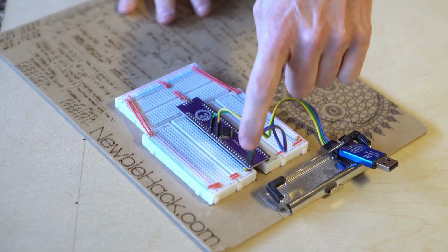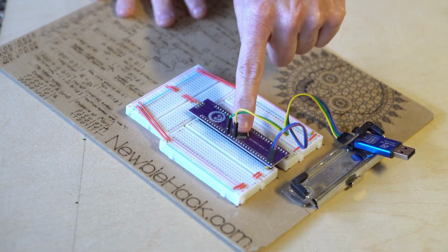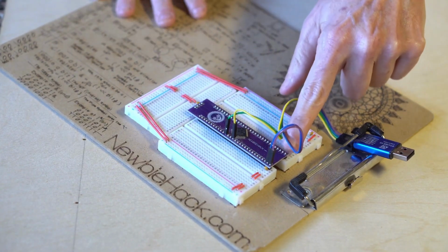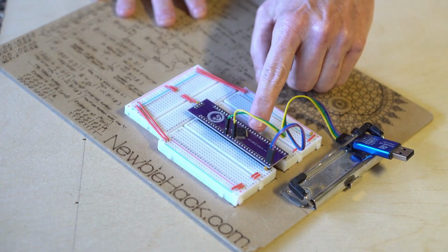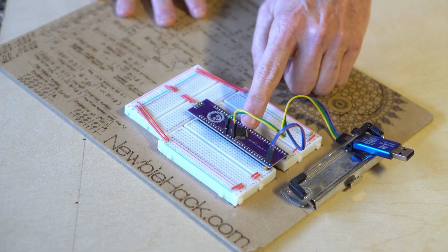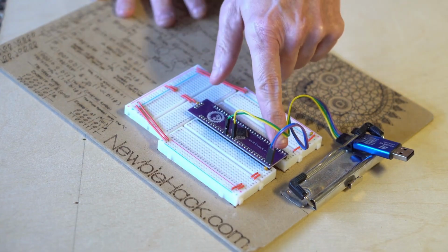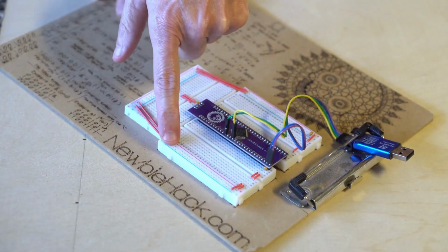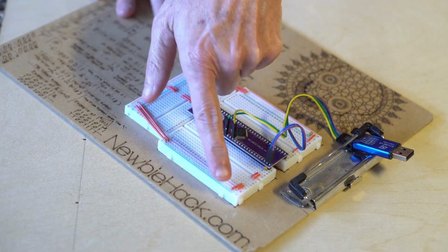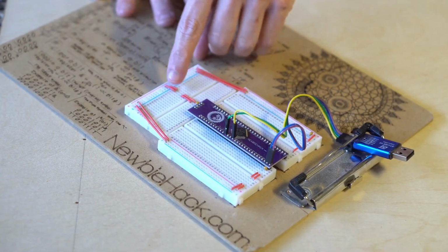The power pins of the microcontroller need to be connected to multiple pins on the microcontroller. These two pins here, these two pins over here, and this one pin over here. It can also be connected to a couple pins over here that's used for the analog to digital converter, but you only need to use them when you're using that converter. To be able to power the pins that are around the microcontroller, you need to connect the breadboards all together on the power rails. There are two power rails, one for the plus and one for the minus. And then those pins are connected to those power rails.